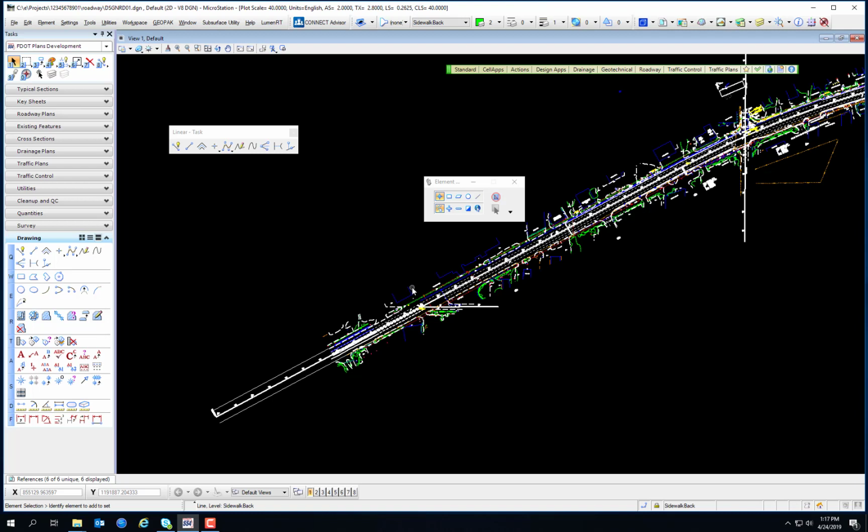So let's talk about the Polygons task, and then we're going to come back to the Smartline task apparently. Polygons task is right here. It's below the linear task. You can right click and select Open Polygons as toolbox. There's a Polygons task toolbox. And while it is possible to create closed polygonal shapes using the Place Line and Place Smartline tools, it is often easier to use the tools contained in the Polygons toolbox.